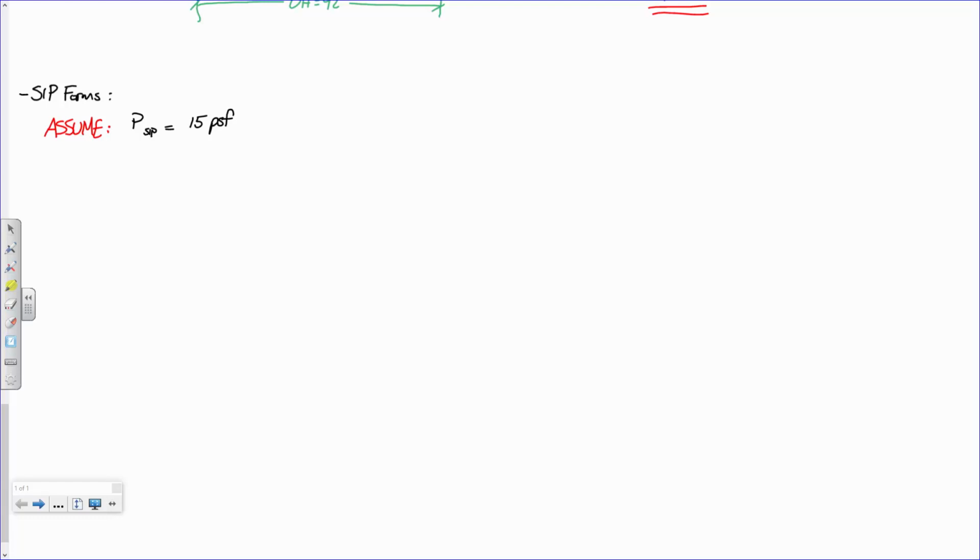The easiest answer to your question is this. First off, you actually need the forms. You need to find the Steel Deck Institute manufacturing guide to figure out what forms you're going to use. Once you have that, you'll have the geometry of the form so that you can determine the area of that little channel. Then the area times the length gives you the overall weight. And I don't even think you need to do that, since a lot of these formwork guides have that listed.